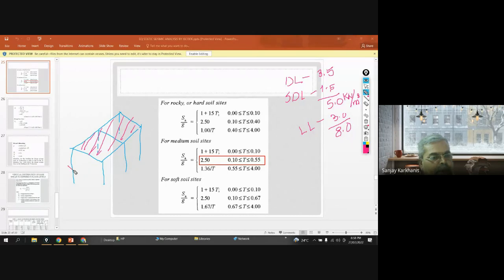There may be, let's say this is your 50%. So this is your wall. Accordingly, you have to consider all walls with half of the height of the wall, plus all columns.